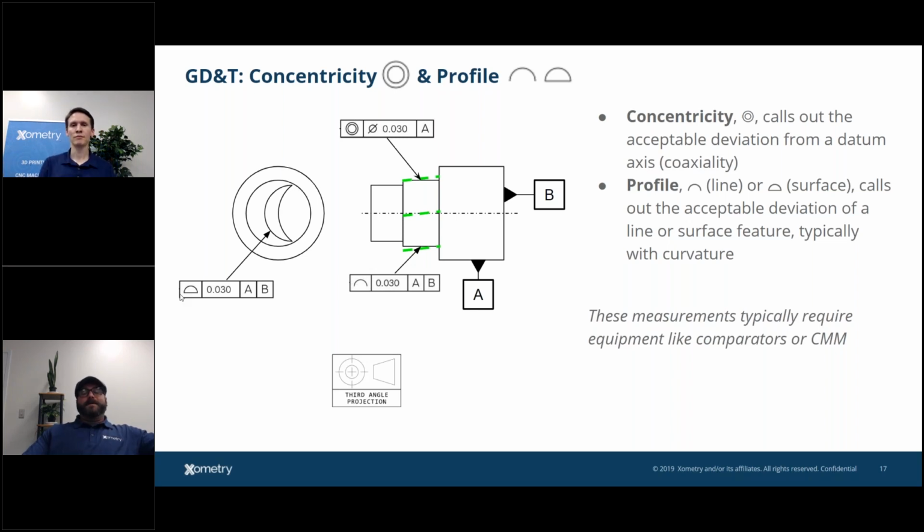Yeah. The other thing is, I've seen a couple engineers who use surface profile as their only tolerance on the part. Don't do that. It makes inspection a nightmare. Then we have to CMM every hole. And when I say CMM, I'm not just doing four touch points to make sure the hole's where it's at. I actually have to do a scan of all the holes, all the features on the part, that then have to be scanned.